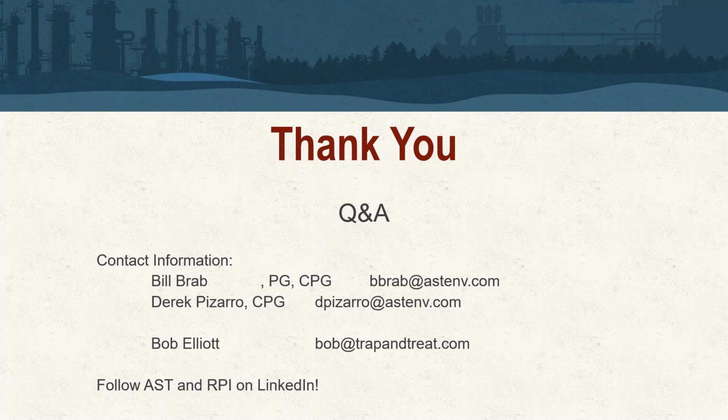Another question here. What happens if you're pulling free phase product directly out of an interval that you're testing? What do you advise in that case? And I guess to add a little bit to that, this is probably during the discrete sampling. Would you continue to sample that interval or that fracture, or would you shut that down? I personally would continue to pull on it to remove mass from the system. Also, we can remove product from an interval and put that in a sampling container and utilize the LNAPL, or the DNAPL in this case, from the site to actually calibrate the instrument at the laboratory for analyzing any sort of dissolved or sorbed phase that may be present specific to that contaminant at the facility itself. Sure. All right.